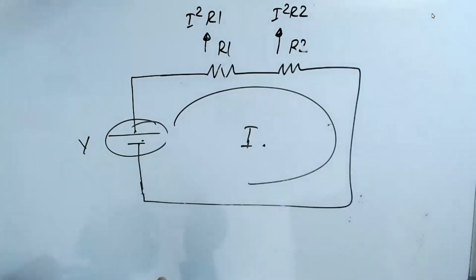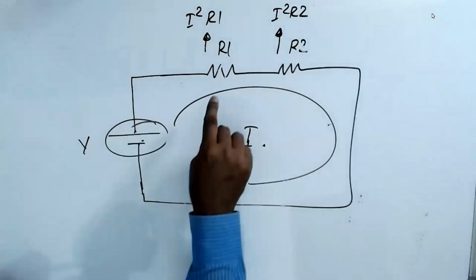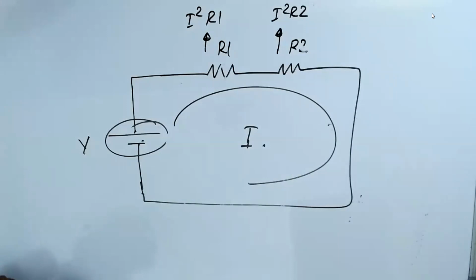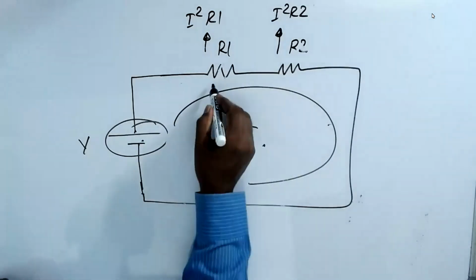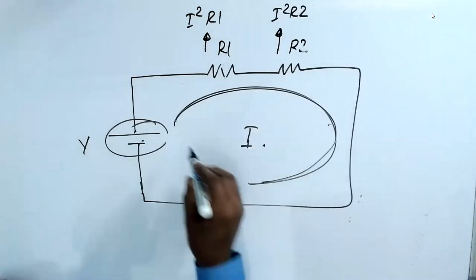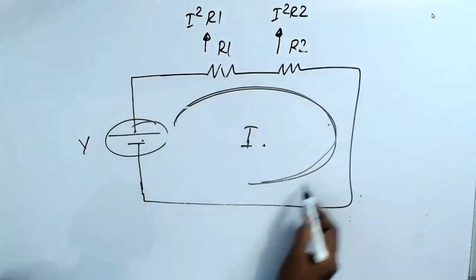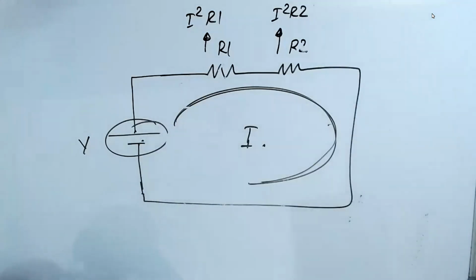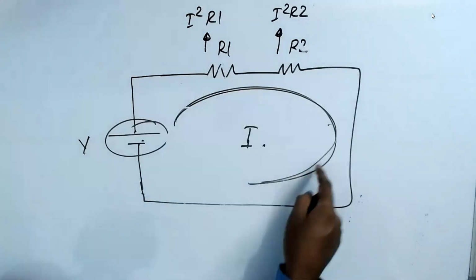Do you understand? We have a circuit, but now I have two resistors connected in series. Since they are connected in series, this current is common, because the electron starts from here, flows through both and comes back. So there's no way it can be different. If you connect a single circuit, the current is common.